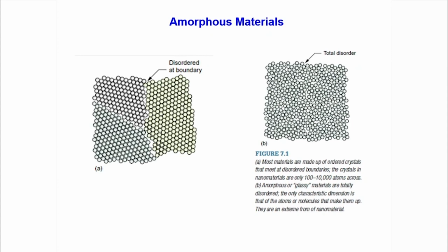And you know, many amorphous materials are there. Glass, window glass is an amorphous material. Ordinary glass, what you call, correct? Even you have metallic, ceramic, other ceramic materials which are glass. Polymer materials are also present as glass, correct? Among them are polycarbonate, acrylic or plexiglass, or polystyrene, which is used as one of the materials for dress materials. The Burgers vector of dislocations cannot be defined even in an amorphous material, right?